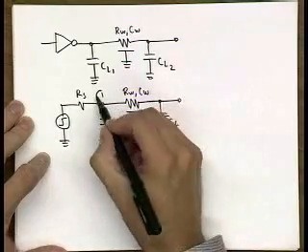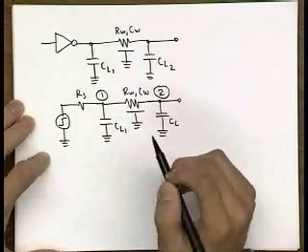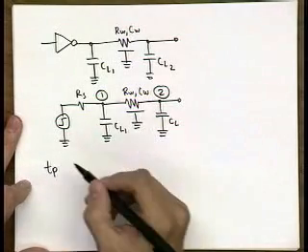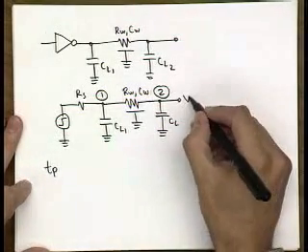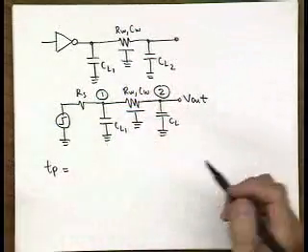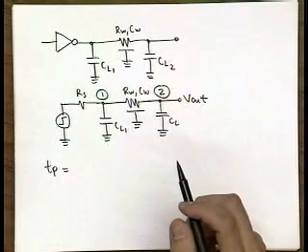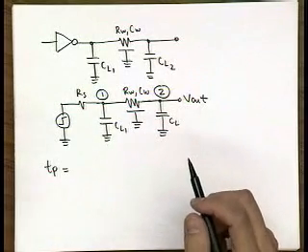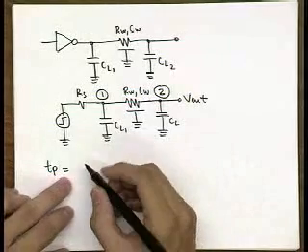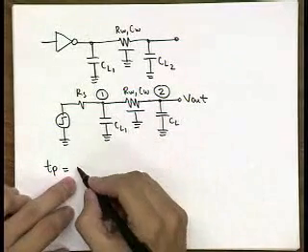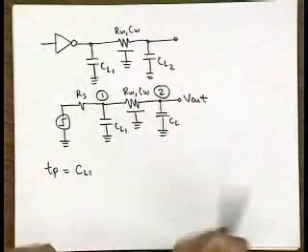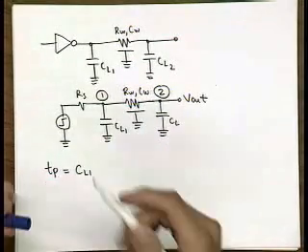So let's label this node 1, node 2. So the propagation delay of this entire network would be equal to the following. Let's now apply Elmore delay analysis, because that's what we're familiar with. It's really nice for this kind of complicated structure. So let's start with node 1. We have CL1, and going upstream to the source. So this is the path we are interested in.